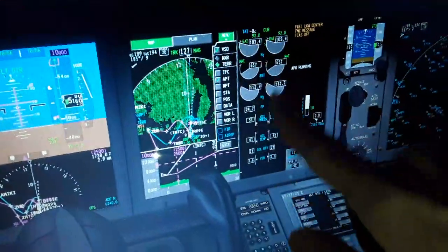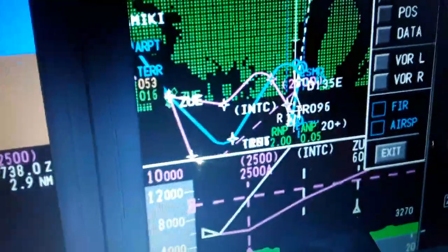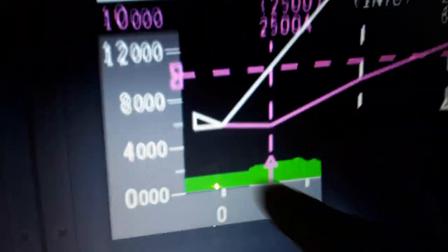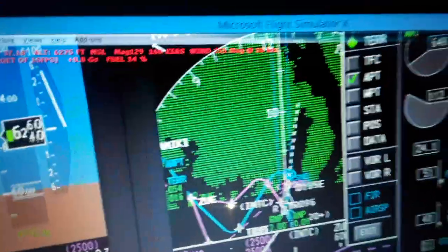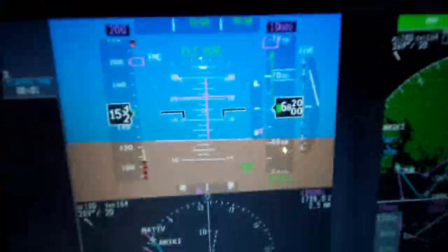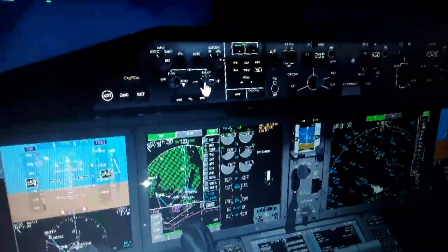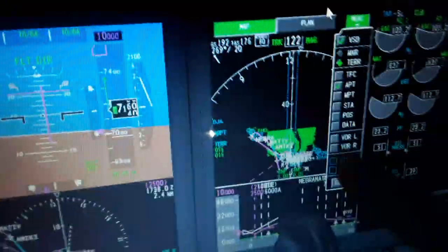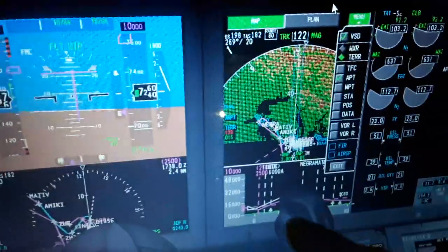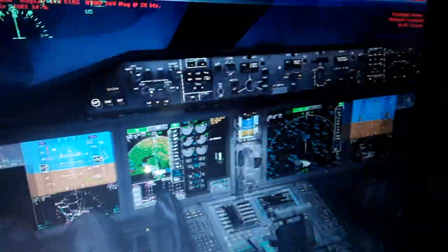The stall speed you'll see later, the pitch attitude of the aircraft, also the engine's indication, and also the terrain below you as displayed. You can see we are like 2,000 or 3,000 feet above the ground, and you can see the terrain, this red green indication in the vertical display, also the horizontal over here around you. You can see also the stall speed here, with yellow and red. We need to avoid the stall, and also we can look a little bit further where we will see more terrain with red, green, and also the flight plan we need to follow.